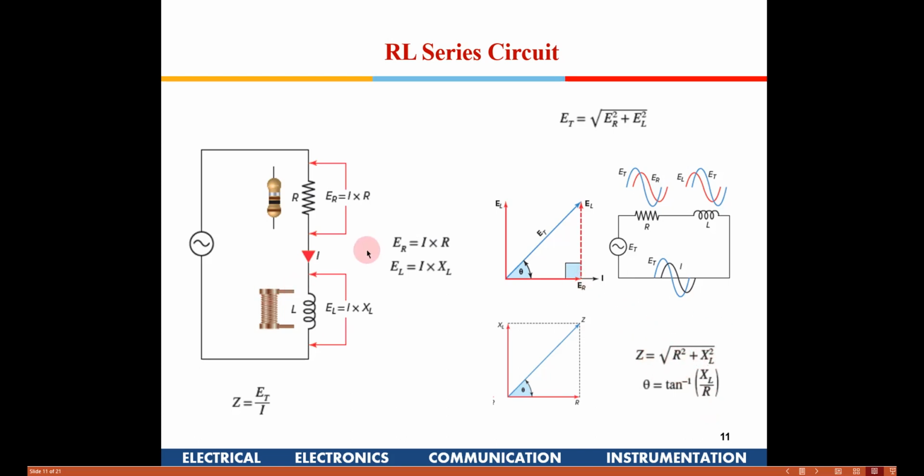So in this circuit, as the frequency keeps increasing, the current will keep decreasing, right, because it is L omega. So here there is no resonance or anything like that. If you keep increasing the frequency, the current will keep dropping because the impedance will keep increasing linearly. Since there is an inductor, the current is always going to be lagging only. There is no way the current can lead, because you have just a pure R and L in this circuit. So this is a series RL circuit.